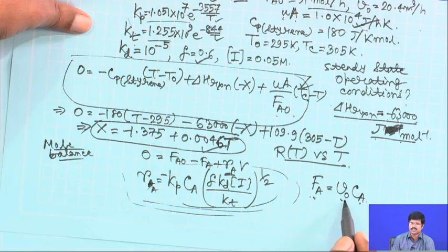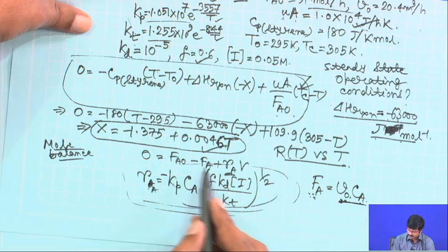Now, V0 is the inlet volumetric flow rate. This is also equal to the outlet volumetric flow rate, because both are equal in the case of liquid state reactions under steady state conditions. That is why I am putting V0 here, even though this is the molar flow rate out. So, just put those values in here.